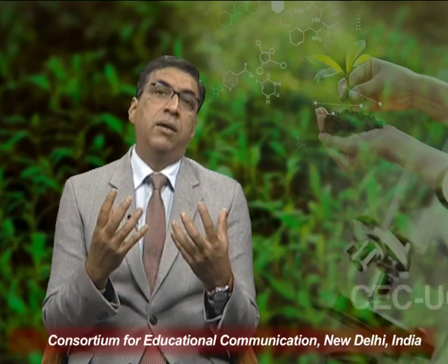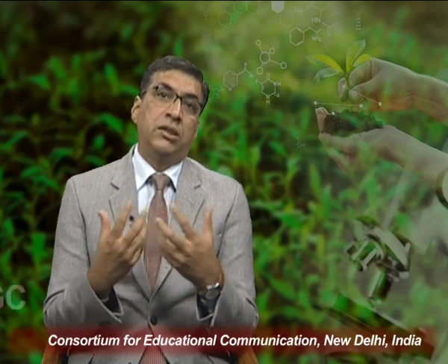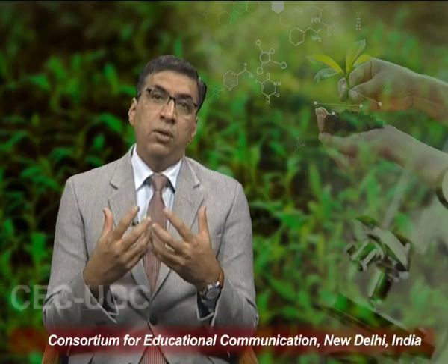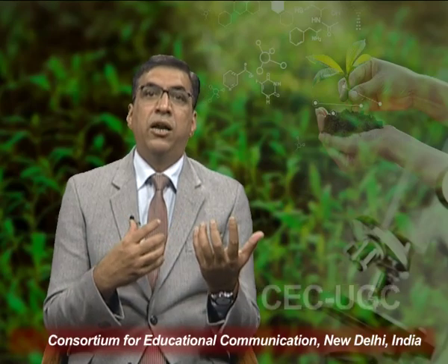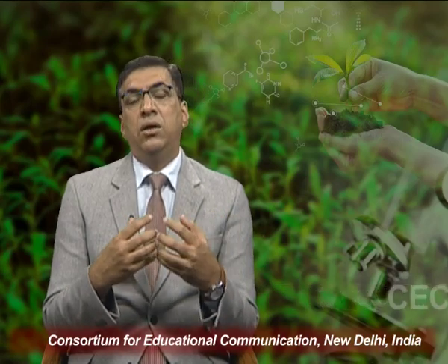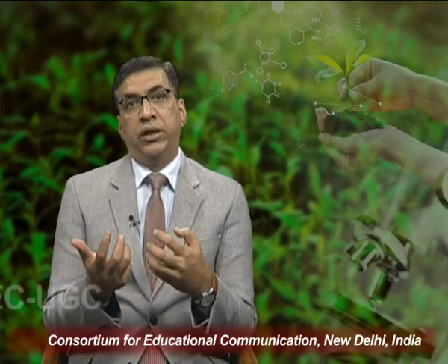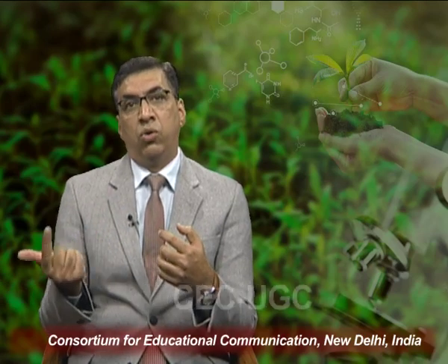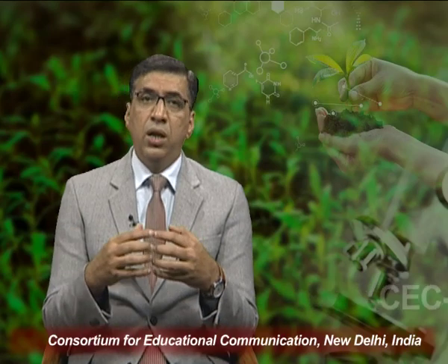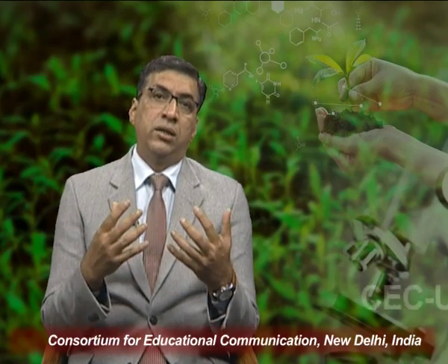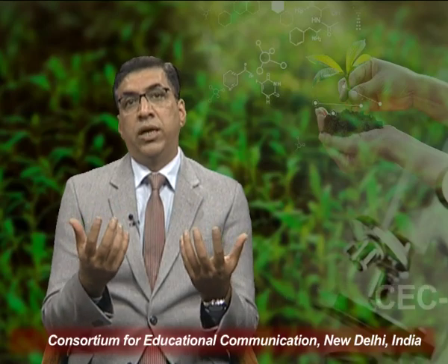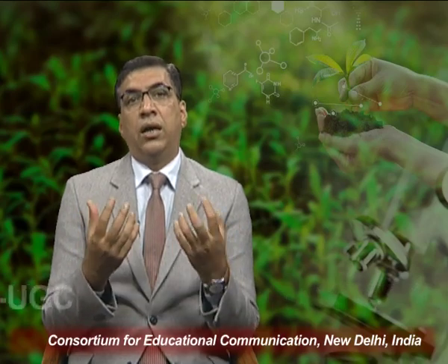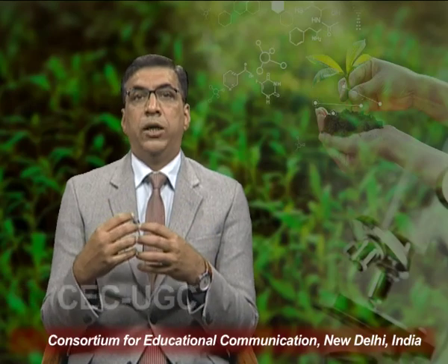And if that ability to transfer the effect or mixing power into the bioreactor is achieved only at a high impeller tip speed, it will increase the shear stress in the culture media, thereby hampering the overall growth of the cells. Therefore, it is always recommended that the impellers have the ability to transfer the circulatory power throughout the culture media and the bioreactor, but it should be done at a lower impeller tip speed.